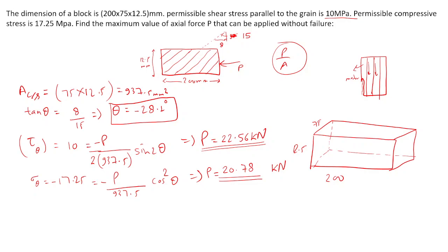Sir, here we are considering the uniaxial stress condition. Here we directly took the condition of uniaxial loading, like the first case, since only uniaxial loading is given in the problem itself. If we remember the general formula, that is also okay. So simply put sigma y as 0 and tau xy as 0.